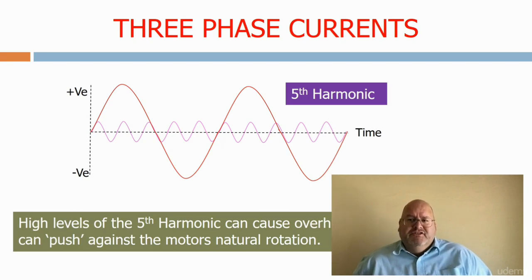Harmonics are an unavoidable feature of an alternating current system. They can be useful indications of equipment going faulty, but can also have serious consequences for an electrical utility. I once worked for a client in London who had to replace over 2,000 televisions for customers, all located in the same area. Upon further analysis, it was found that an old power factor compensation unit was causing serious harmonic distortions that caused the damage.